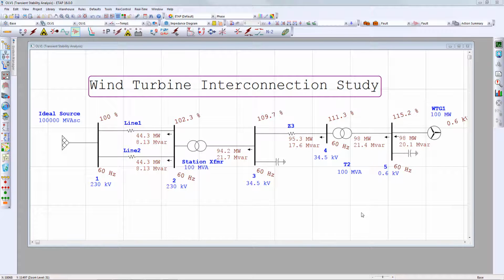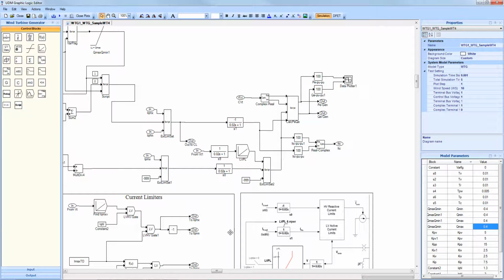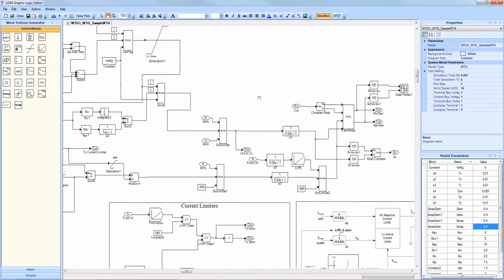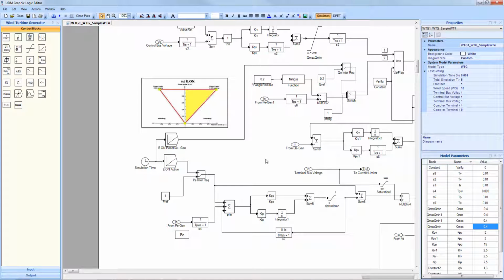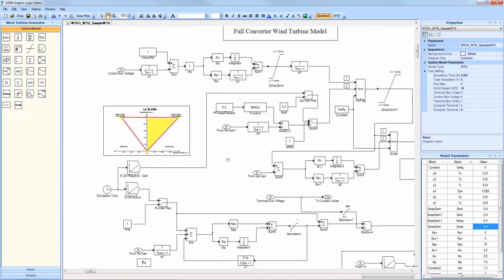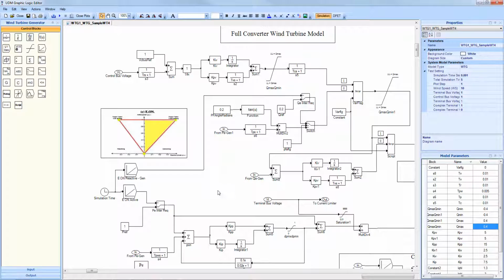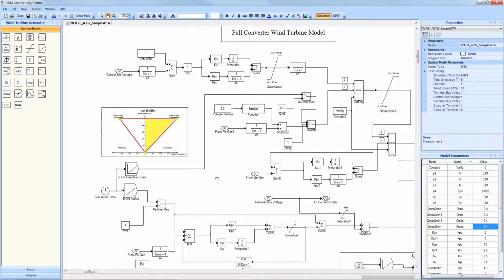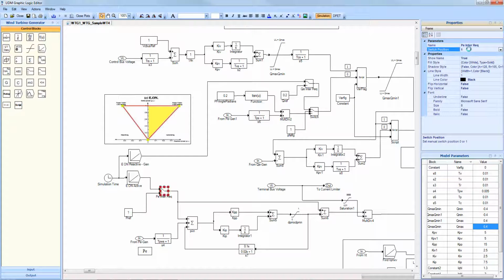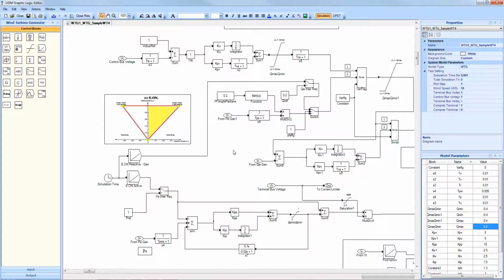Now we can do a final simulation of our wind turbine system where we can represent the interconnection study and how changing reactive power demands will be based on different active power injection into the utility or network. Before we can run that simulation, we must make a couple of changes to our diagram where we'll inject, instead of single reference generation, the reference map for the interconnection requirements. A simple change on our switch blocks at these two locations will allow us to pass the new reference values.